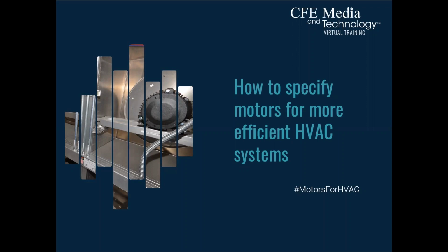If you have a 6-pulse VF drive, you will get 5th and 7th harmonics primarily. If you have a 12-pulse drive, you will primarily have 11th and 13th harmonics. With an 18-pulse drive, which you typically see for larger motors, there will be few harmonics because the harmonics have a tendency to cancel each other out when you have an 18-pulse drive.